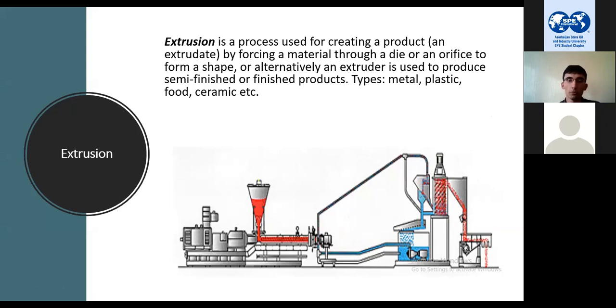Our pure product is sent to the extruder, and in the extruder, as you can see in the photo, there is a screw. As it rotates, it mixes and transfers the melt throughout the extrusion unit towards what we call the die plate.